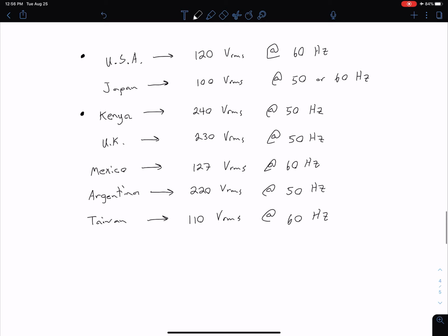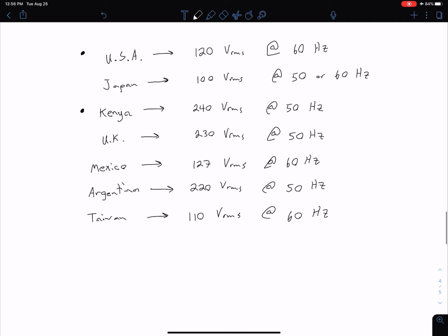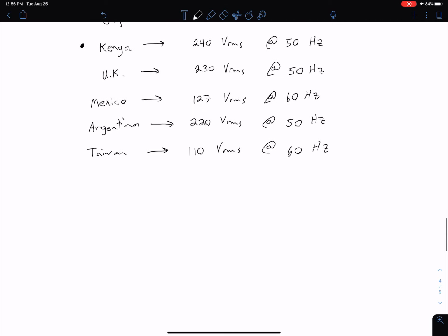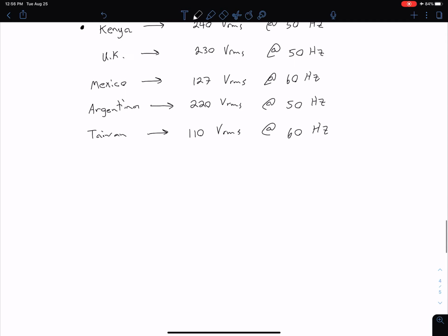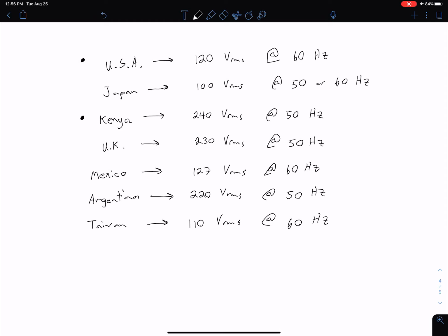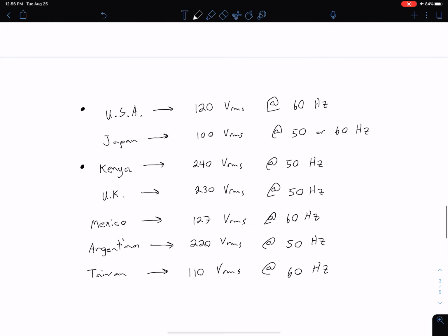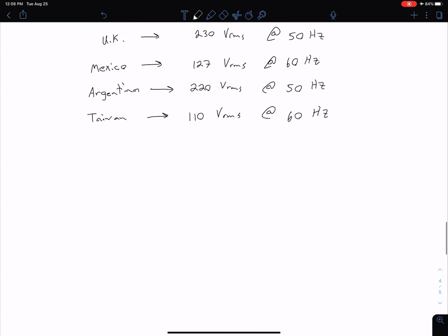Some of these other places I've just used as examples because they give a good variety of our RMS voltage. Going back to that idea of a universal power supply, if we want to design a power supply that's going to work everywhere, one other thing we need to consider is that the AC utility voltage coming from our wall outlet generally varies by as much as 10%.